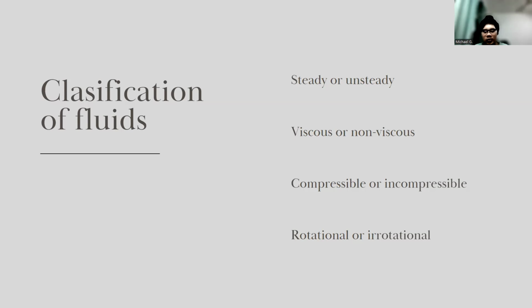If the angle between the two intersecting lines of the boundary of the fluid element changes while moving in the flow, it is a rotational flow. Depending on the angular motion of the fluid, it is classified into rotational flow or irrotational flow. If the fluid rotates as a whole with no change in angle between the boundary lines, the flow of the fluid is classified as an irrotational flow.